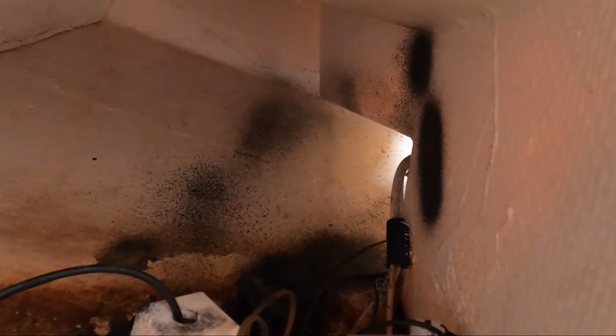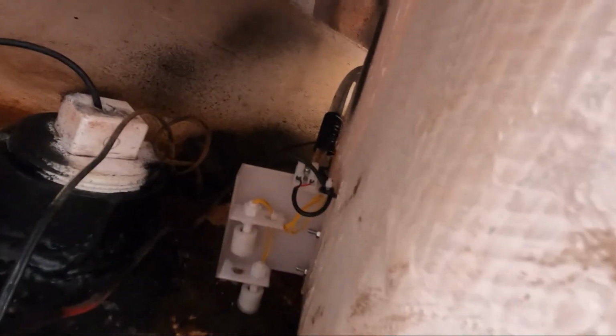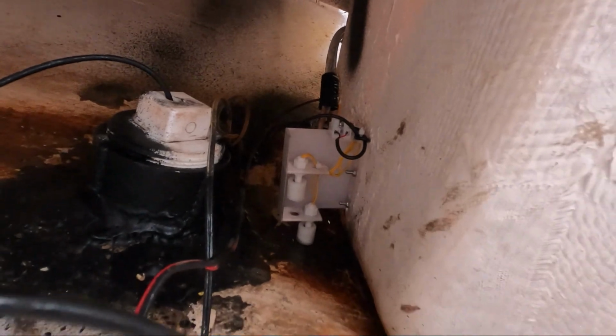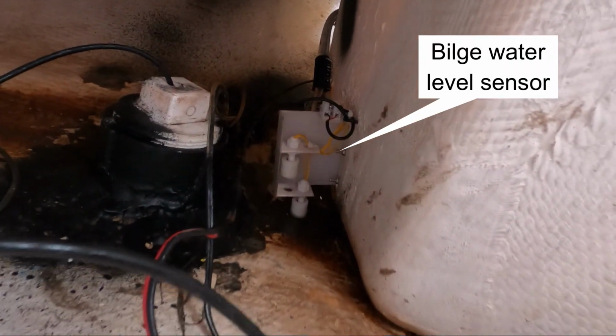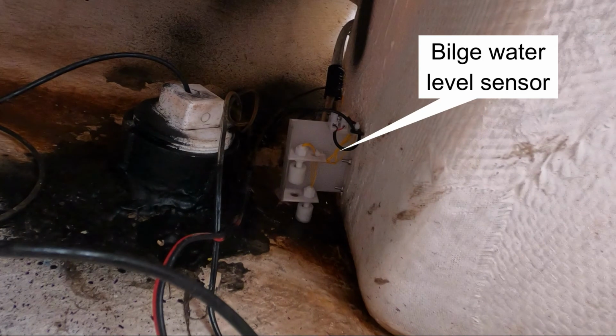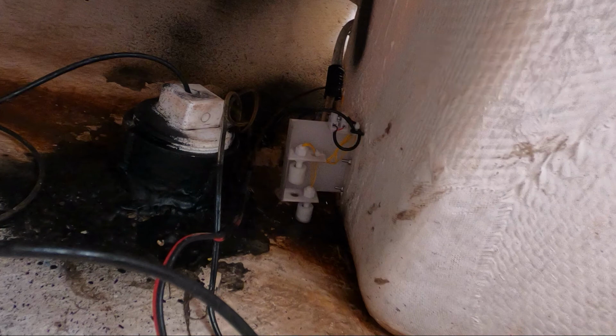And the bilge monitor is up here in the front, where you can see it there. There it is up against the face of that fiberglass there. And as those two sensors rise, that's when it'll set up a resistive ladder and send the signal back to the actual bilge monitor.